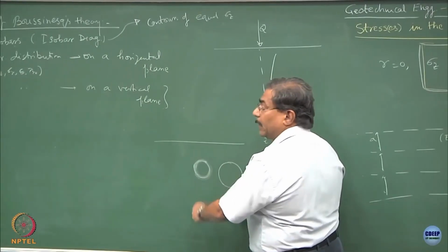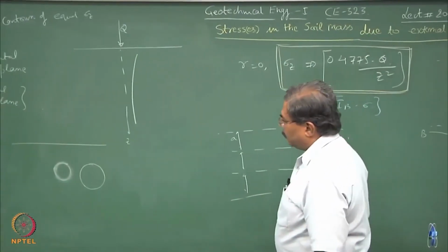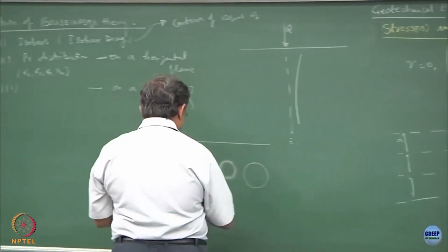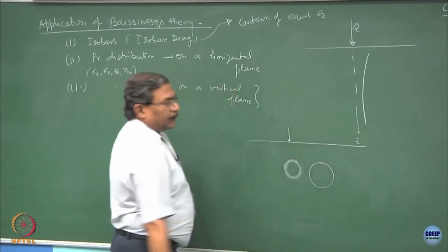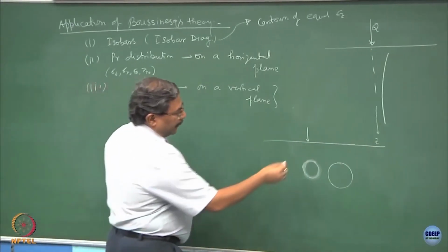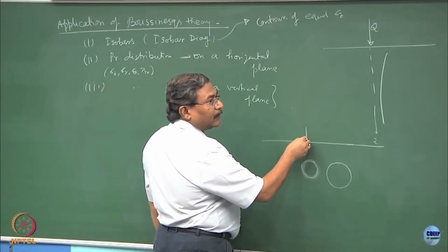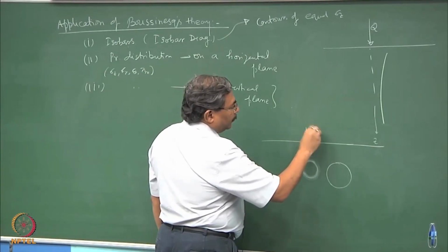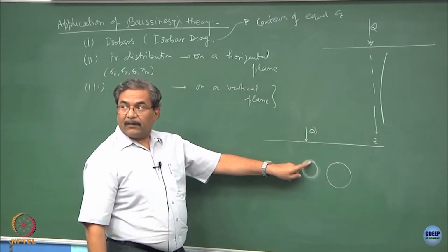Every time I cannot be so lucky, so then you have to do engineering based on the material properties. Anyway, giving you an example, suppose this is how the load comes, and I want to see whether this pipeline is going to get influenced because of the external loading or not. If I know the value of Q, I can find out the state of stress at the crown of the pipe.